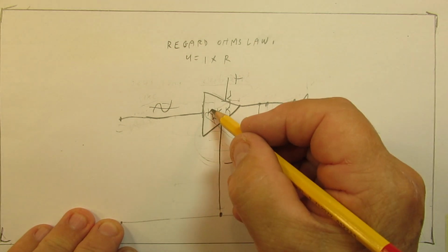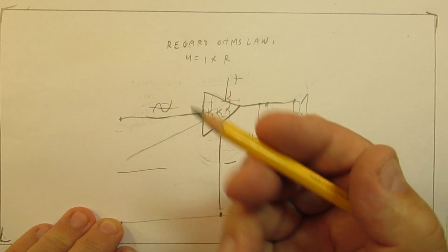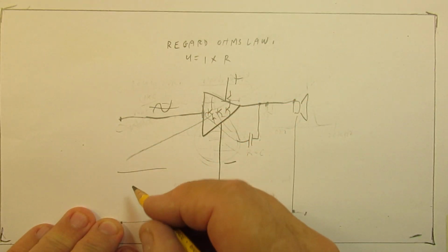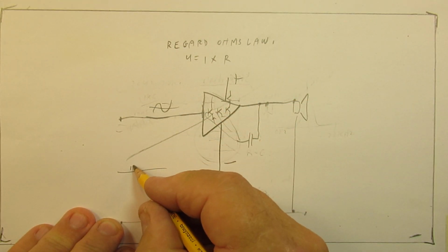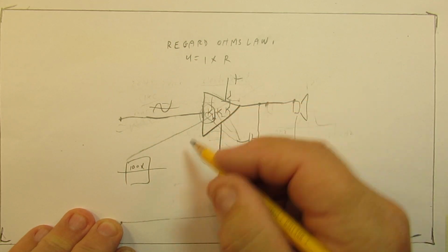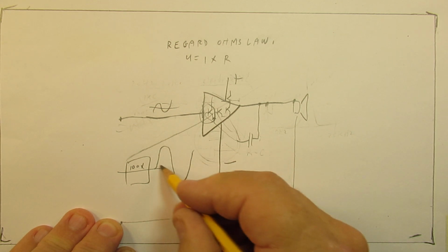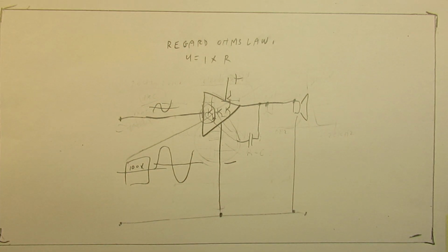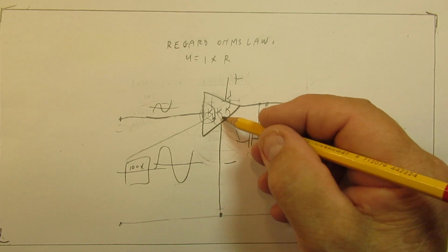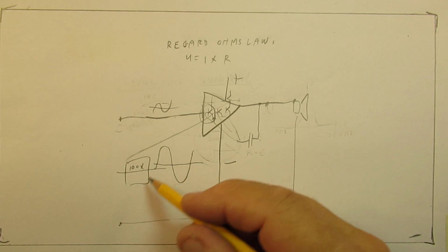So in the first transistor it's often amplified perhaps 100 times, could be 100 times. And when the transistor is biased properly, there is a real good sine wave here. On the second transistor, it could be that it is amplified not 100 times, because that's a lot.